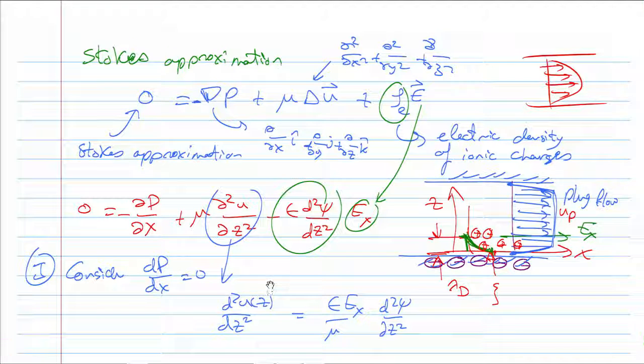Okay, good. So you don't have u partial u partial x, and you don't have v partial u partial y, because there is no v. So all the left hand side, as far as we consider, is cancelled. On the right hand side, there is a pressure gradient, and so this would be 0 in case there is no pressure, running against no load, and this would be maximum in case, basically I'm asking you what is the maximum pressure you can drive at.